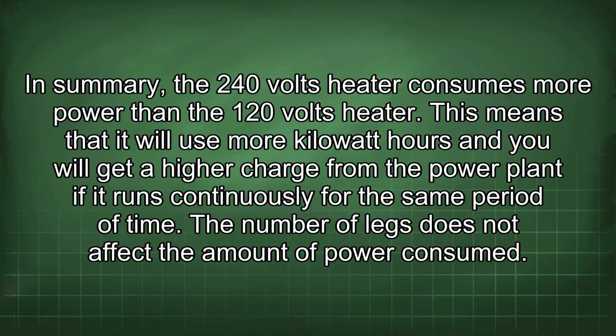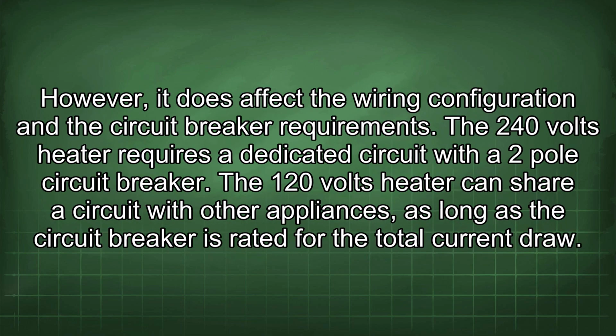In summary, the 240 volts heater consumes more power than the 120 volts heater. This means that it will use more kilowatt hours and you will get a higher charge from the power plant if it runs continuously for the same period of time. The number of legs does not affect the amount of power consumed. However, it does affect the wiring configuration and the circuit breaker requirements.